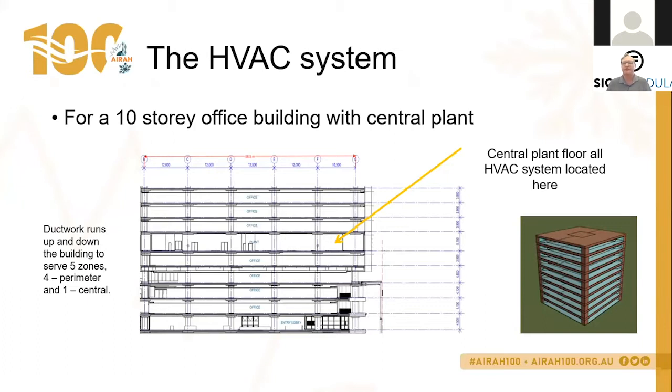There are sensors in each floor level. We have 5 AHUs within the central plant room, and we have the ability to bring the outside air via a single system direct to each of those 5 AHUs, or we can duct to the 5 AHUs separately. This determines how we would then design the economy cycle or the demand control ventilation requirements.